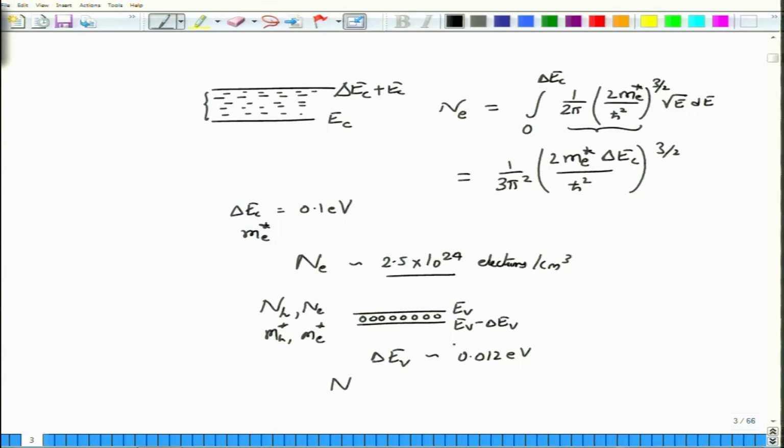Okay. Now, we need to look at how much current is required to maintain this amount of carriers. Before we do that, we need to know a little bit about the lifetime of the carrier. What we mean by lifetime is the characteristic time over which electrons can combine with holes and emit a photon. This is of course applicable in the direct band gap cases, as we have emphasized repeatedly. This lifetime is, let us say, tau pH, and the current required to maintain this amount of carriers will be about Ne divided by tau pH, and this is the current density.